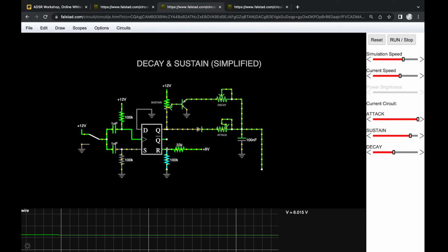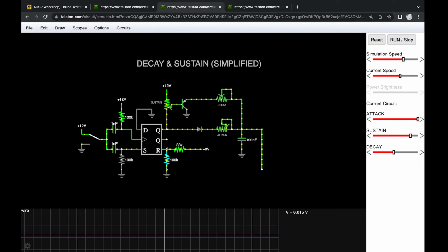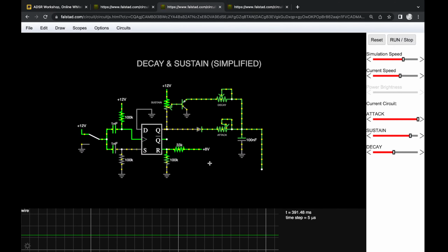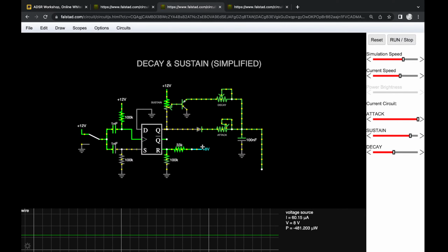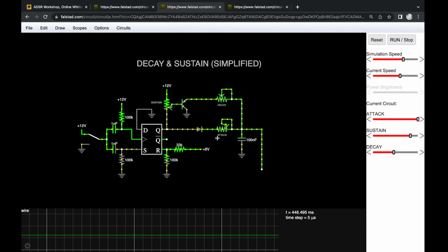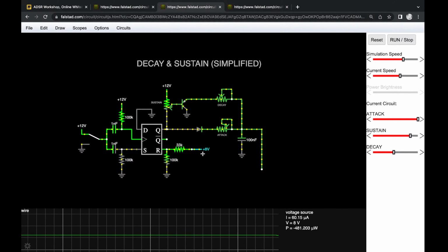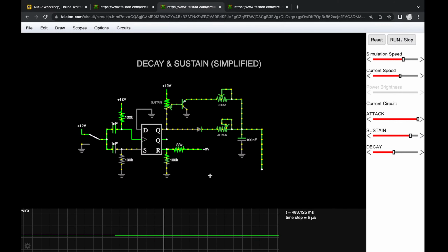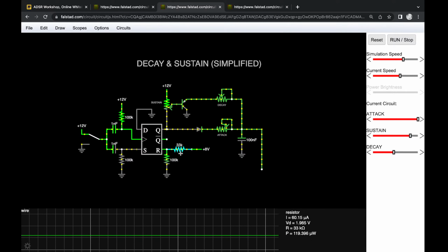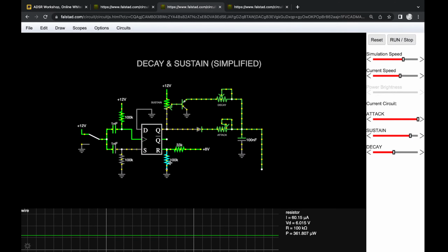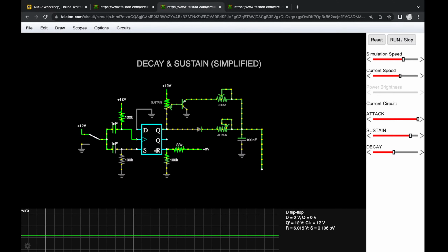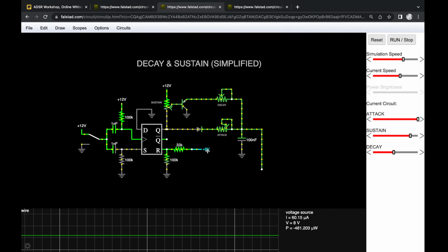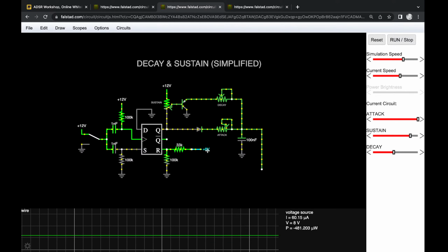Yes. So with this voltage divider, we only get 6 volts at the reset input if our envelope's output sits at 8 volts. That's how we increase the peak. Before it was 6 volts because we didn't have a voltage divider. Now the flip-flop would shut itself off at 8 volts, which is what we want.